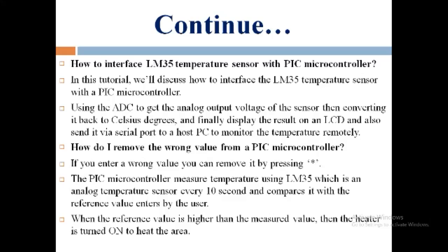The PIC microcontroller measures temperature using the LM35 sensor, which is an analog temperature sensor, every 10 seconds and compares it with the reference value entered by the user. When the reference value is higher than the measured value, then the heater is turned on to heat the area. There is an indication that the heater is on.